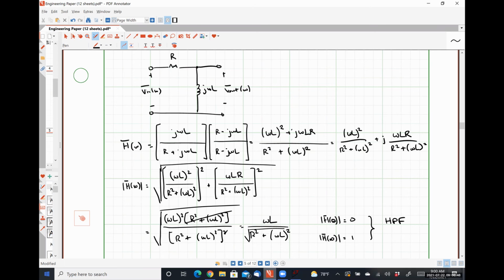Yeah. So waveguides are all about the size and the shape of an aperture, which is just the size of the hole that lets the signal pass through, right? So if you have very, very tiny holes, it's going to reject a bunch of low frequency things, and it's only going to pass things through where the wavelength of the signal is 4 times as long as the diameter of the hole.